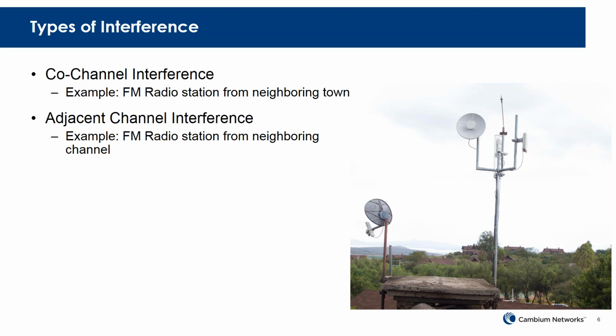Well, as you drive from your city to the other city, at some point your radio is going to begin cutting out on your home station and cutting over to that new station. They're both on the same channel, and now at that point, that other station is starting to interfere with your station. And we've all experienced that, driving down the road. And so that's a form of co-channel interference when both are on the exact same channel.